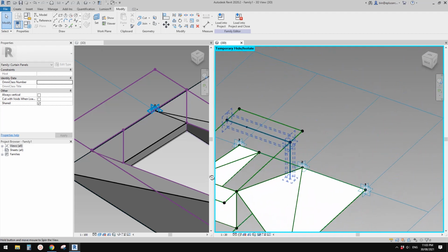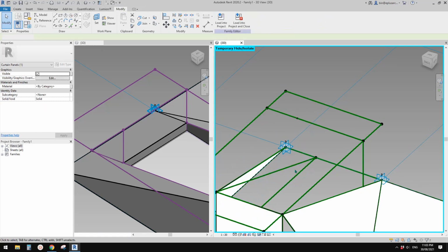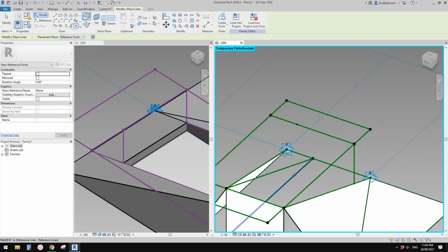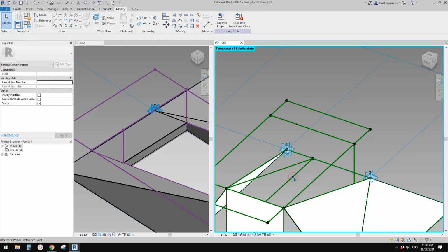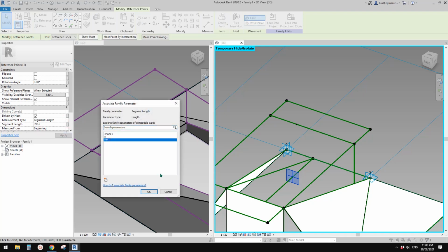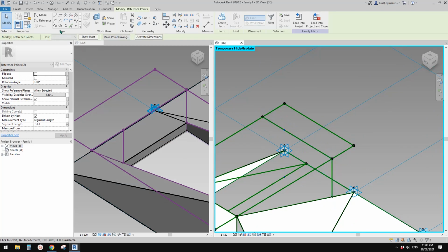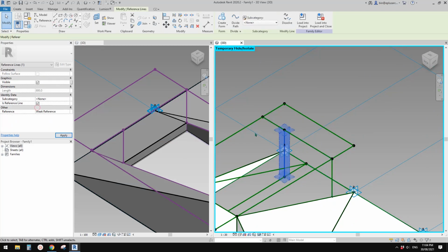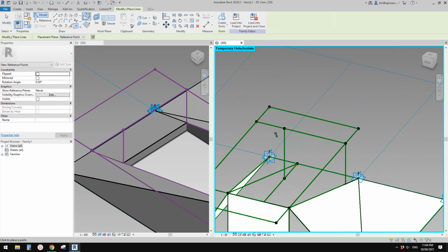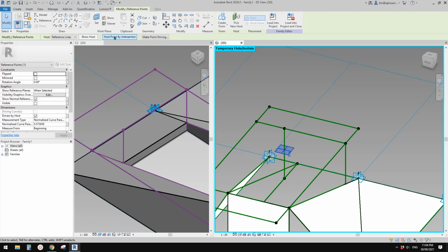So okay, we just need to do the same. I'll HH all the face. So point, draw on face and place it on a reference line. That's correct. Segment length, link this to FW, frame width, and then create another spline and place a point, draw on face and place it on this reference line, and use the intersection, pick this reference line.